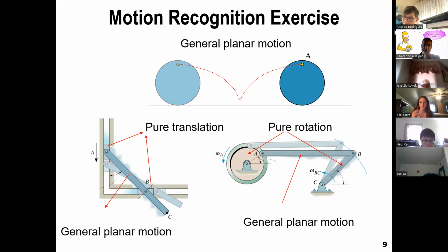These are examples of, when you analyze the motion of a rigid body, understanding what is parallel. The pedal itself, considering you put your foot at a certain angle, like horizontal, as it goes up and down, is technically translational motion. If you do not tilt your foot, the pedal itself is always parallel to the ground and has a curvilinear motion, moves on a circle, but does not rotate. Does that make sense? So that's how we analyze the motion of rigid bodies.